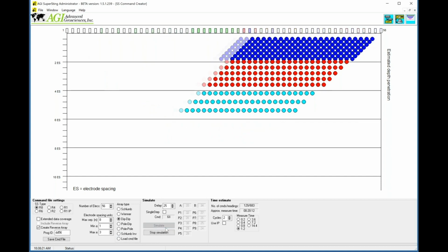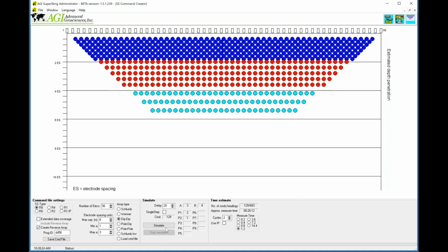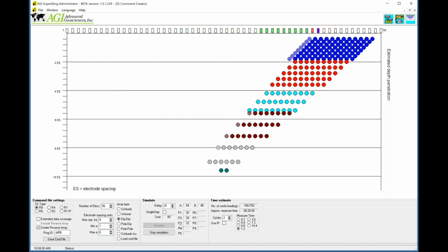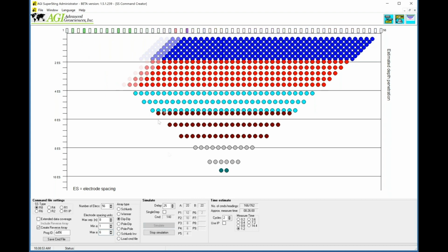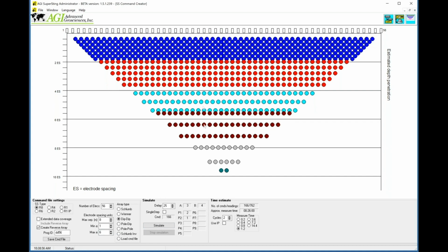Now here, notice it only takes 20 minutes. So I cut 6 minutes off, and we're not getting this deeper data. So that's a quick way of collecting the near surface data, which is always stronger. And if you're doing a DOT project, this is a way of doing it a little quicker and just the strongest data. But really it's 26 versus 20. So that extra 6 minutes, if you're going to go to the trouble of putting the cable out, I would suggest collecting this as well and maybe trimming that off if you need to. So hopefully that answers that question.